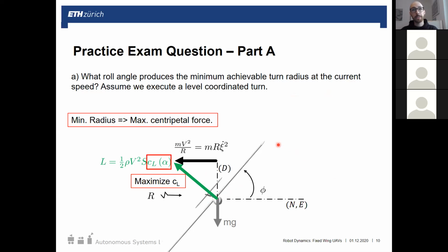In wind, as we've defined wind in this lecture, we're only considering steady, constant wind. So no transient effects, no force effects on the plane, only once it's settled and we have a velocity component for wind in the inertial frame. Since we've defined wind in this way, as just a velocity component that's added to our airspeed to get ground speed, this won't change the lift vector either, because wind is defined as the whole air mass's movement.